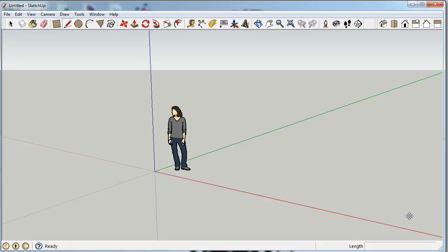In this video, I'm going to walk you through the necessary steps to complete the bubble wand design activity for Tech Adventure Camp. The first thing we're going to do is make sure that we have the SketchUp window open and we have our preferences set so that the units of measurement we're currently working in will be set to millimeters. The reason why we select millimeters is because that is the best unit of measurement that can be transferred over when creating the STL files and the files that are necessary for creating the actual 3D print.